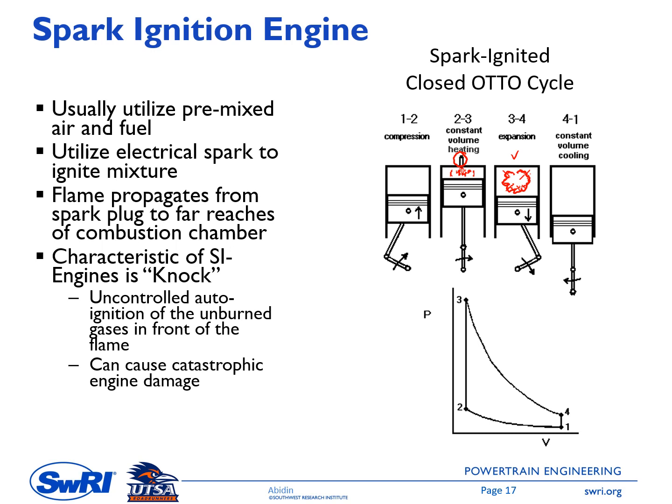Another characteristic of this spark ignition engine is knocking. Knocking here means that the unburned mixture will auto-ignite, so it will ignite by itself because of the increased pressure and temperature, and the temperature is above the ignition temperature. So you have a flame here, and when knock happens, there will be additional ignition ahead of the flame, maybe at the edge of this chamber.